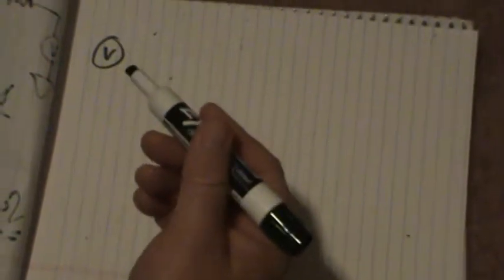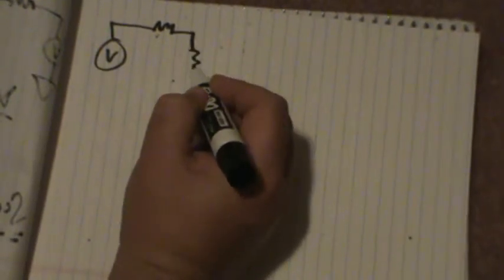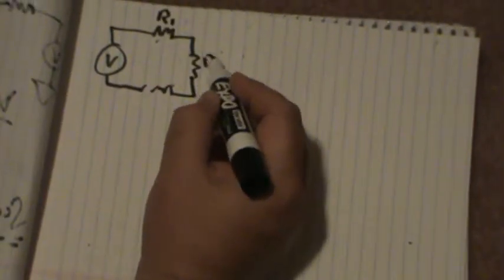So what we did is we were doing mesh analysis, mesh or loop. Mesh is a specific subcase of loop analysis. Mesh requires a planar graph, i.e. there's no loops that kind of jump over it. I can draw it all flat in a plane with no components overlapping. And in a mesh, no mesh should have any other mesh as a sub area. So I'm going to redo the one that I did there as best I can.